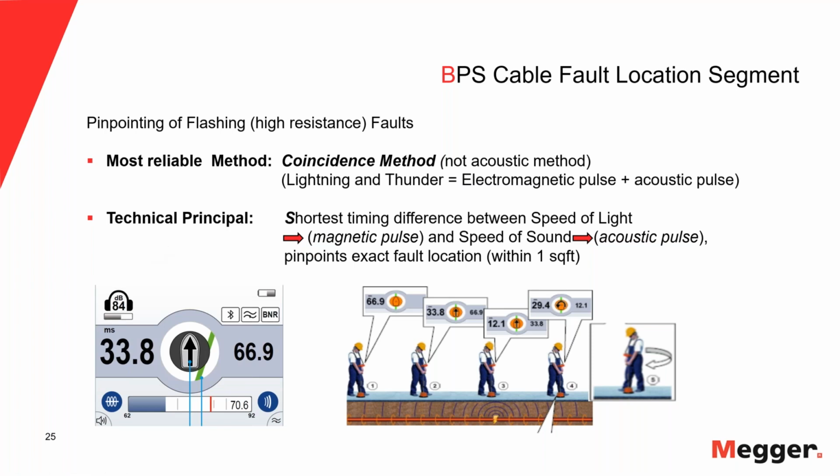You have to move in the direction of lower numbers. And once you're over the fault, you're at the lowest number. And once you pass the fault, you see numbers go up again. It's a very simple principle, but it's a very excellent principle, because it doesn't rely purely on the sound. Whenever you rely only on the sound, there are many things that can go wrong, and it's not a very efficient method to just acoustically try to locate a fault.